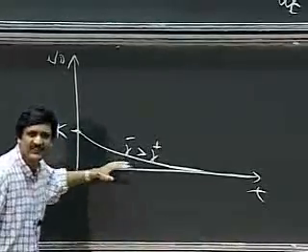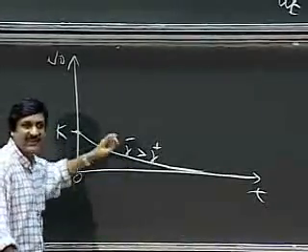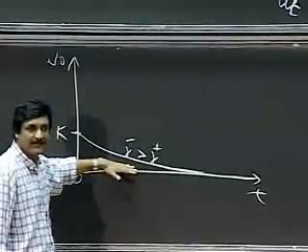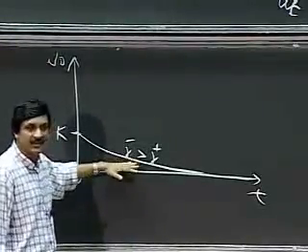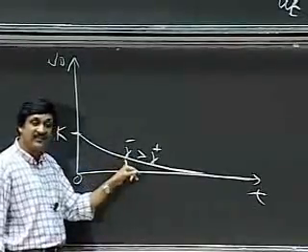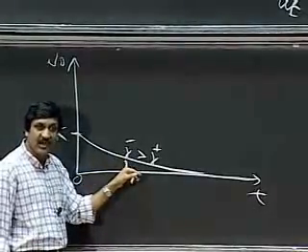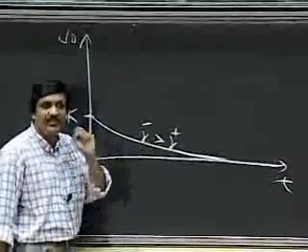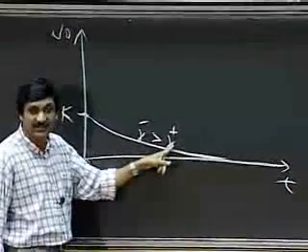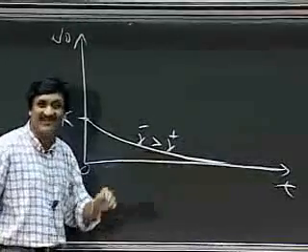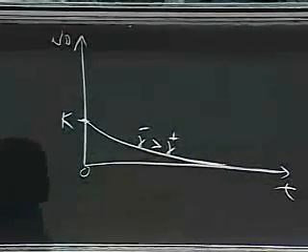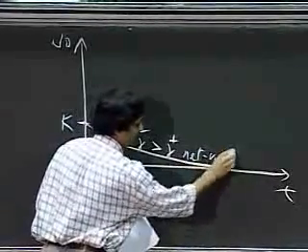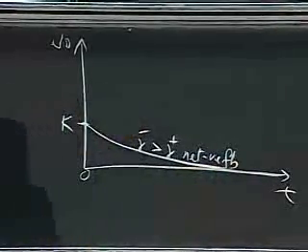So intuitively, what am I saying here? All the gammas and other pieces aside, what am I really saying here in English? What I'm saying is that if the portion of the output fed to the negative input is greater than that fed to the positive input, then I have net negative feedback.